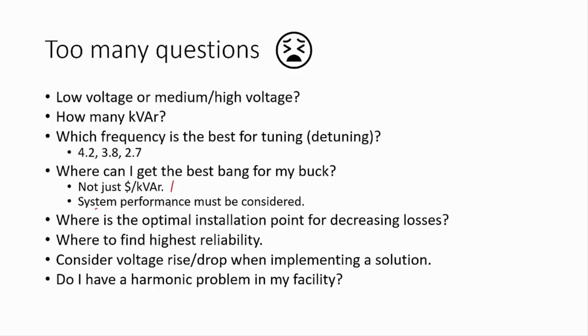When you install the solution, will the harmonic distortion go up? Will it go down? Will there be a voltage rise? Do I have a harmonic problem in my facility right now before installing the solution? So there are many things to consider.